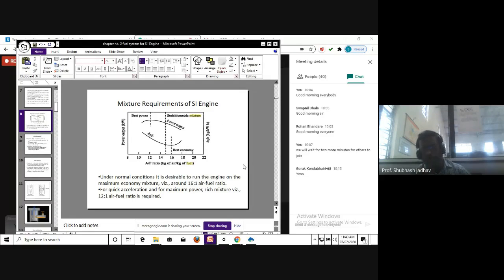Okay, so the speed was affecting, vaporization characteristics are going to be affected, and then temperature may also be affecting, because we are mixing the fuel with the air. Now when we are going to mix this particular fuel and air, the temperature at which we are taking the air is also going to have a considerable effect, because where the fuel is going to get the heat for vaporization is from the air.